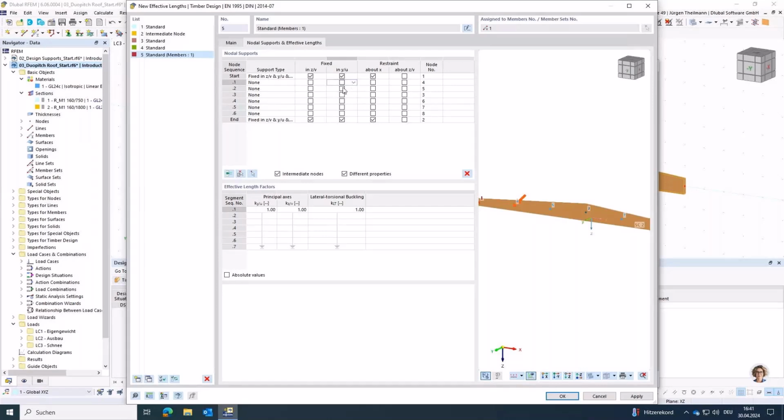And we can simply click on these checks to add the lateral supports, either one by one, or you click the first and the last of those for a multiple selection, then hit on and off as you prefer. And you can see now we have our lateral supports.